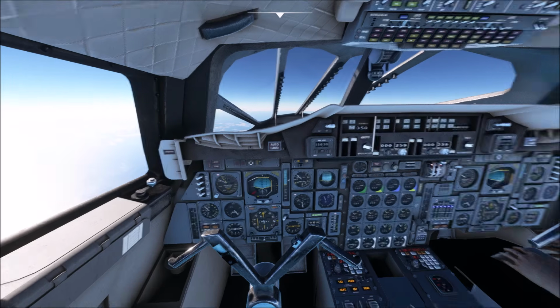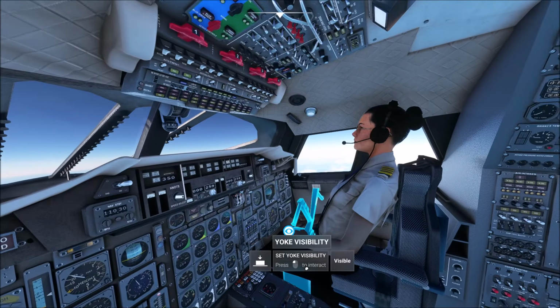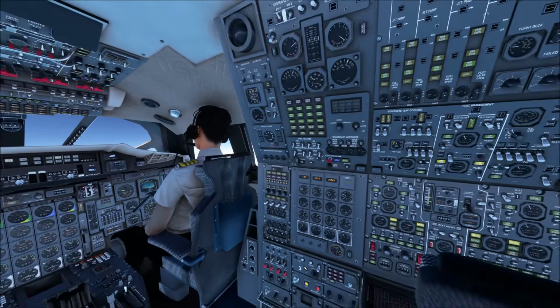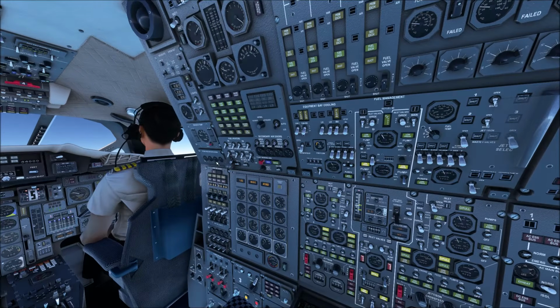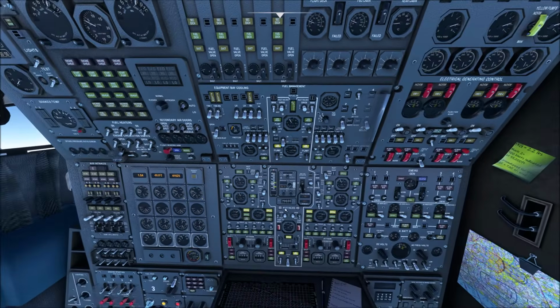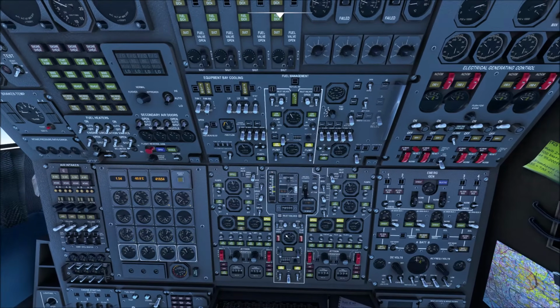Just outside parameters, so I might have to move a little bit more fuel, so I'll show you how to do that for those that really want to give it a try. Obviously this tank is full, so we'll shut the valves here. See, they shut now. Pump auto, we're still moving fuel aft, so we should be able to open the valves.